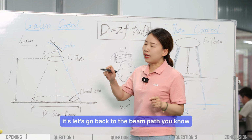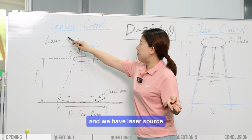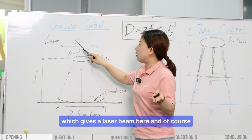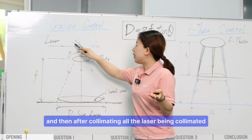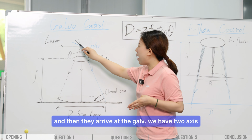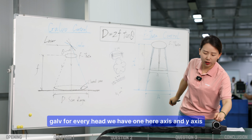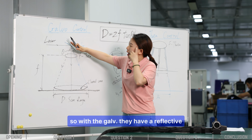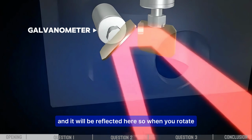Let's go back to the beam path. You know, we have a laser cleaner and we have a laser source, which gives the laser beam here. And of course we have a collimator for the pulse laser and also the CW. Then after collimating, all the laser being collimated arrives at the galvo. We have a 2-axis galvo, for every head we have one, x-axis and y-axis. The galvo has a reflective mirror, when the laser goes in here it will be reflected here.